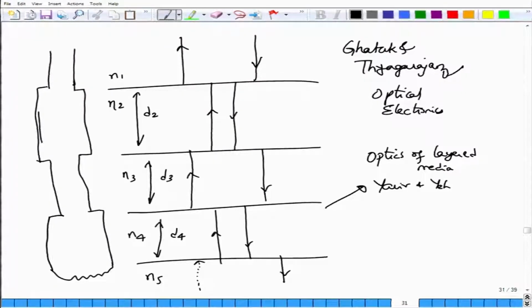So, in between you have to write down the thickness or the length of each of the transmission lines, and you can analyze the problem in this way. You have to successively first find the impedance here, then transform to the impedance here, then transform to the impedance here in order to obtain the overall reflection, and in fact we have asked you to do that in one of the programming exercises given in the first week modules or something, okay.